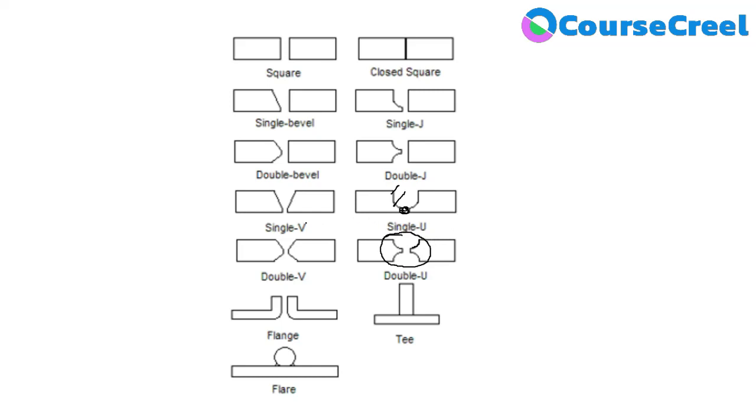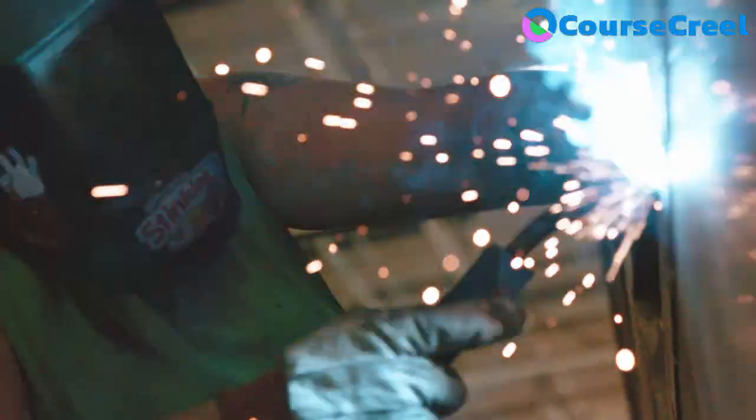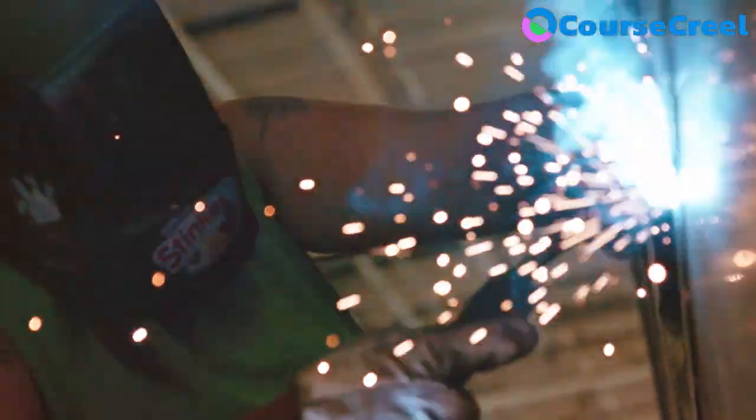So the double U groove and double V groove are the better option for welding when we need more strength or when we want the heat to penetrate to every single point of the weldment. During welding, we need to follow some precautions also, apart from the welding gear. When we are welding, we should use welding gear to protect our eyes and our body from the welding gases and the welding flame.